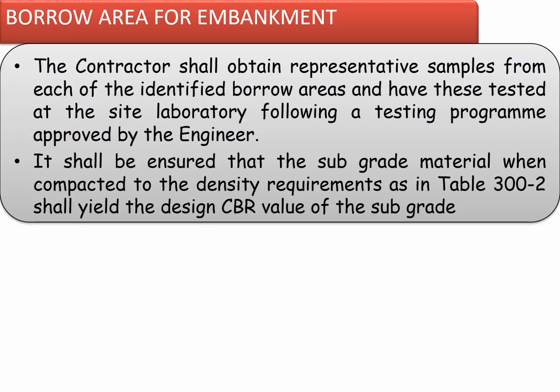The contractor obtains representative samples from each of the identified borrow areas and tests the soil samples in their site laboratory to check the suitability of the material for the embankment. They check the Proctor values to determine the maximum dry density and optimum moisture content.